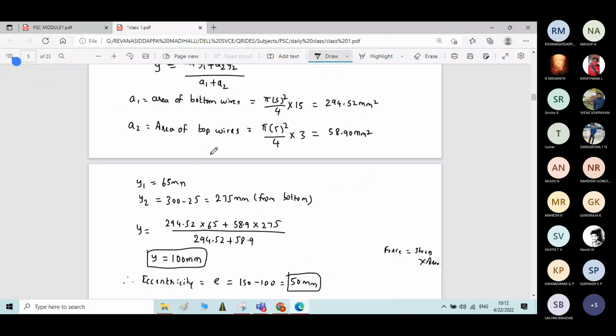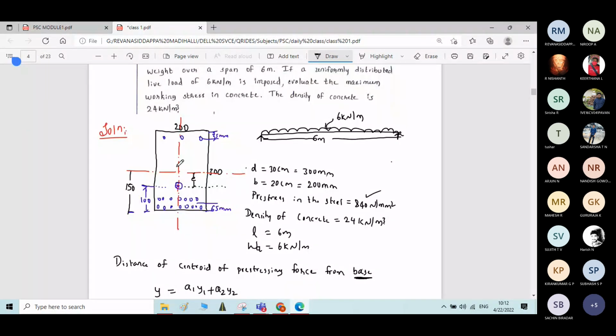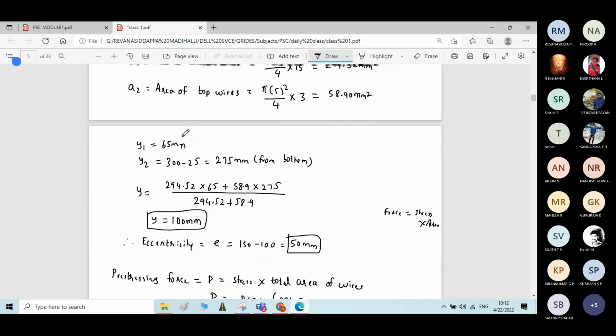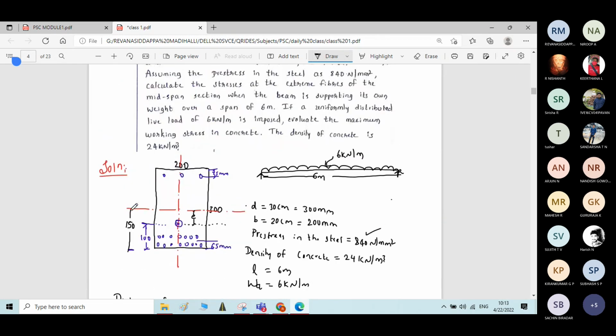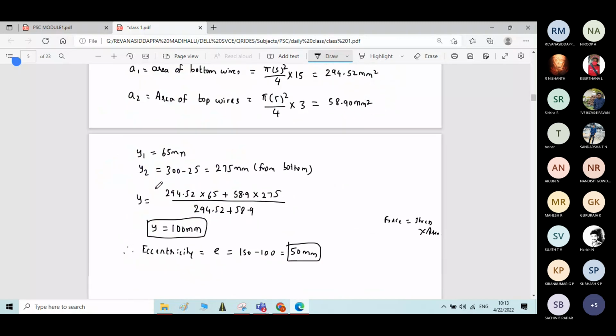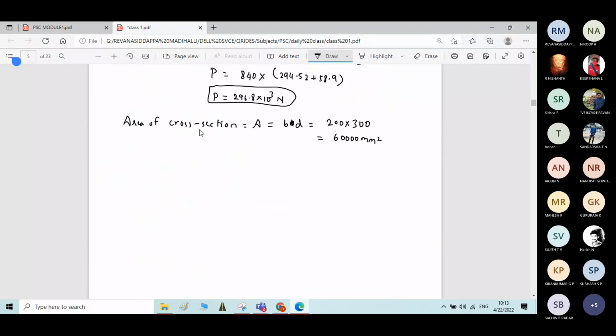Okay, so here it is a rectangle. The neutral axis and central axis both will be the same. So Z will be same for both top fiber and the bottom fiber. So instead of representing separately by ZT and ZB, I'll directly take it as Z because it will be same for both top fiber and bottom fiber, because it is symmetric about X axis. This I explained earlier. Now section modulus, ZT is equal to ZB is equal to Z.